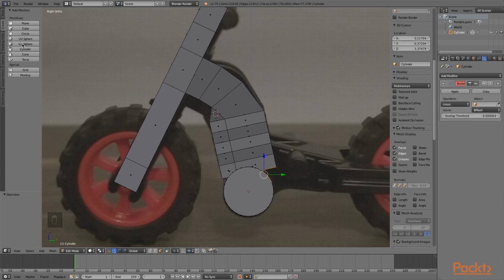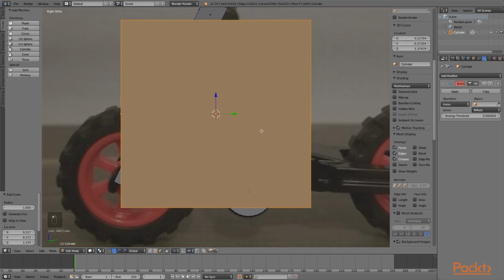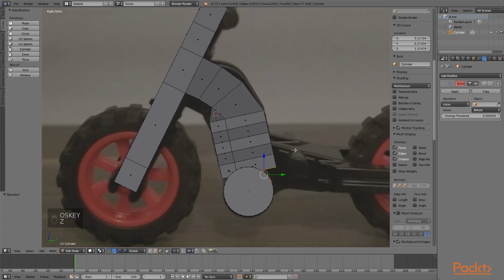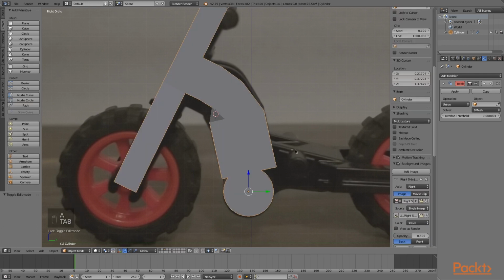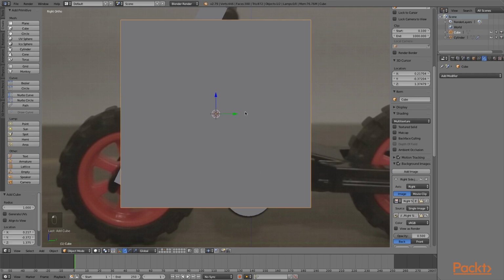So as you can see here, I'm going to create another cube, and you can see that it's not by itself a cube, and I don't want that. I want it to be a separate object if I'm going to apply a modifier to it and take it into the other objects and have it intersect. So I'm going to Command Z to delete that. I'm going to make sure I'm not selected on anything else, and then I can bring in my cube. Now let's fast forward a little bit as I connect these objects and extrude them out to finish the chassis of the bicycle.